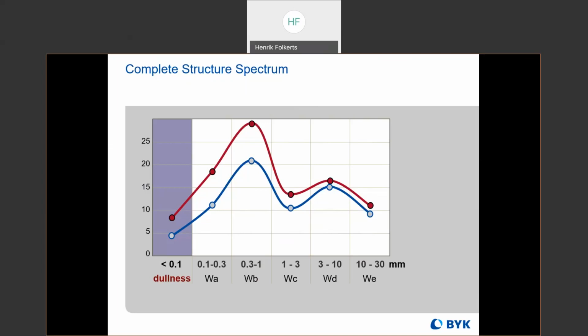Typically, you want a little bit more WB than you want WD, because it helps hide the overall quote-unquote waviness. And you want the WC to be lower than the WD. Like the structure that he's showing you right now is a good structure. You can see on the screen. Sorry, go ahead, Greg. No, it's just what I was going to finish up with, is then looking at not only B and D ratios, but then how C and D play out.